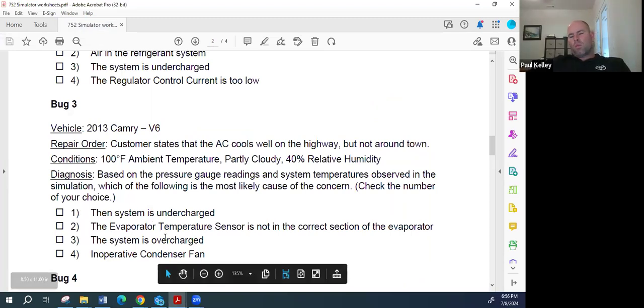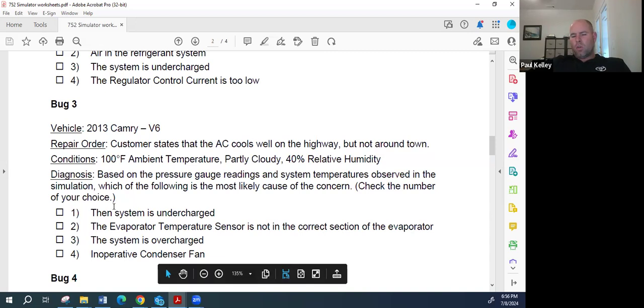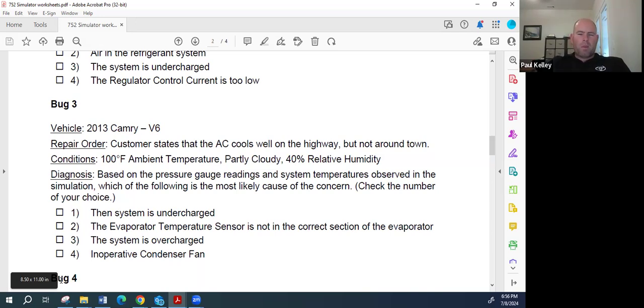So we could eliminate 1 and 3 with that static pressure, right? And then we're looking at 2 and 4, and 2 actually didn't check out perfect, but 2 doesn't make a lot of sense. And there's actually a whole lesson there. Sometimes you'll find something that's maybe not exactly in spec, but sometimes you gotta back up and loosen up a bit and be like, it just doesn't really make sense with the concern. So like, you guys have figured out I end up working on all sorts of stupid stuff. And in my opinion, people who can actually troubleshoot problems is a very small percentage of the population.